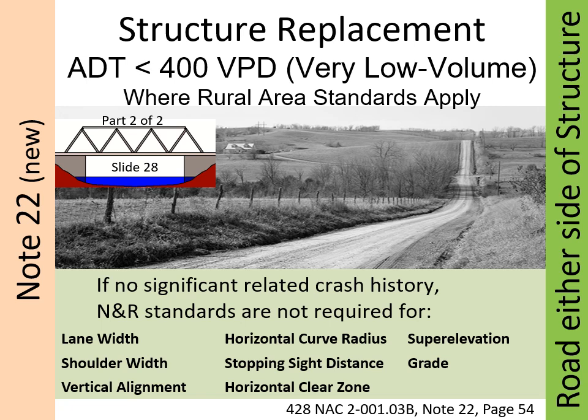Note 22 may be most appropriate and applicable if the grade is the same or approximately the same before and after the work. Use good judgment. It may be best to make an improvement even if standards do not require it. It is important to consider safety continuity and consistency with respect to driver expectation.